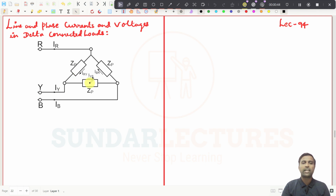This is nothing but a delta connected system. The basics of the delta connected system we have already seen, and you see here which one is the line current and phase current. Whatever current is coming in here will be the line current, and whatever current is flowing through this load impedance, we call it the phase current, right? We know that already. So IR, IY and IB we generally call line currents, right?